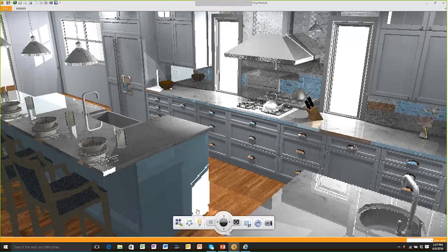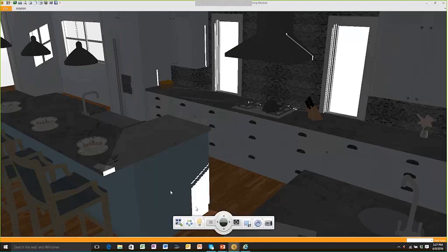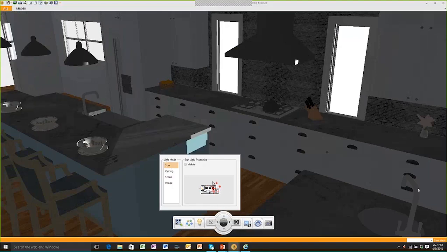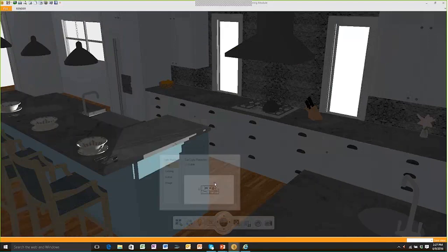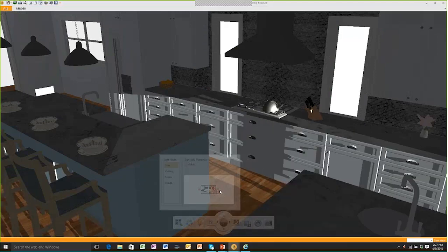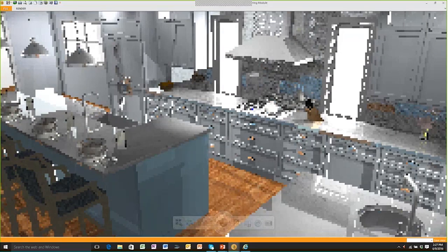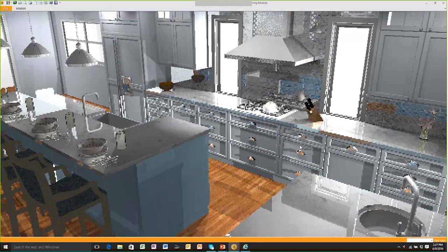Now, at the bottom of your screen, you also have some other options. See this little navigation bar? It appears on the screen. See the little button here called Light? I clicked on that a little while ago. Remember, I clicked on Ceiling Light, said Turn the light on, and I moved it around. Well, you have other lighting options in here, too. I could go to Sun. I could take hold of the sunlight, and I could actually move where the sun is in the sky and adjust the shadowing in the room based on the sunlight. So let's say that we put the sun outside of the patio door. I'll go ahead and click it. When I click here, it'll re-render based on that sunlight pattern. So you'll see reflections, shadowing, light bouncing, light being absorbed, depending on where the light is in the room.